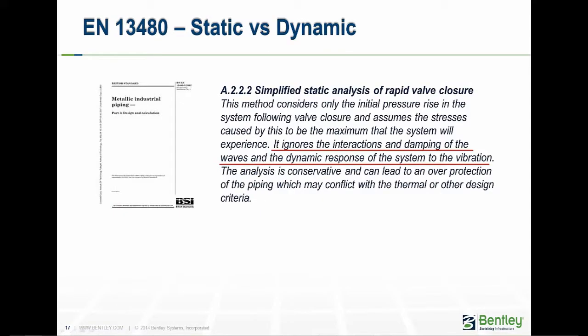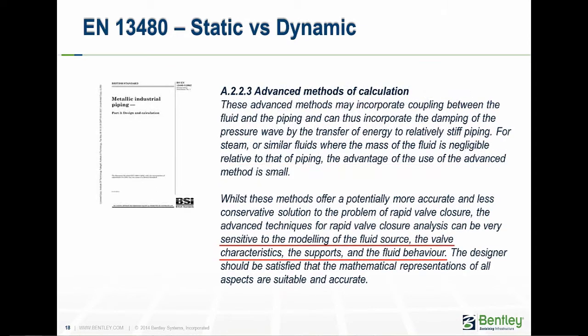The Eurocode has some advice on considering dynamic and static loads. A simplified static approach ignores the interaction of waves and the dynamic response of the system, and is usually conservative. The dynamic approach can be considered more accurate, but is highly sensitive to the characteristic of the valve closure, supports, and fluid behavior. It will also be sensitive to missing modes if a modal analysis solution is used, so the designer should ensure that all the significant modes have been included and be comfortable with the approach.